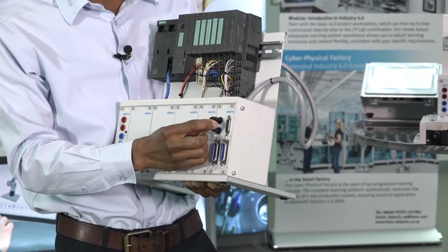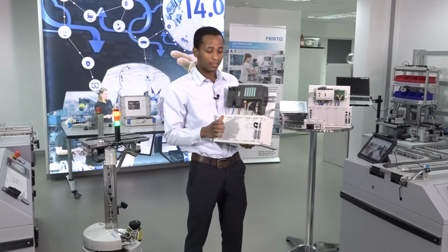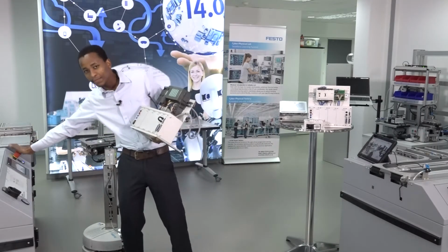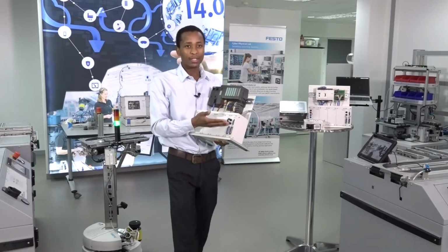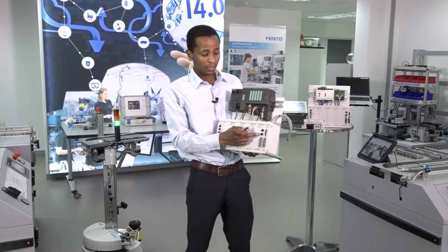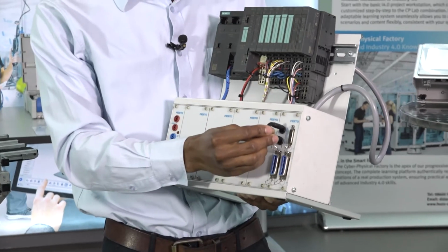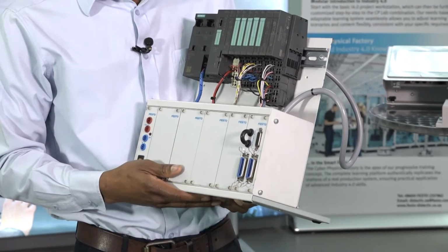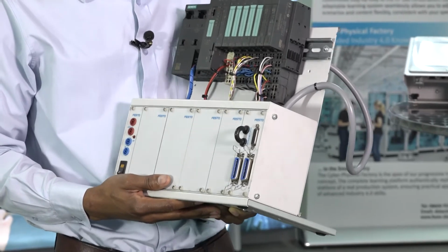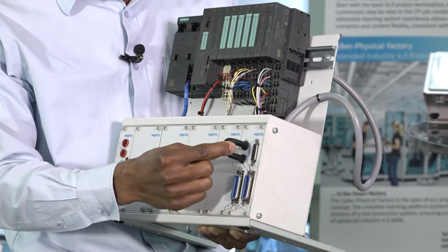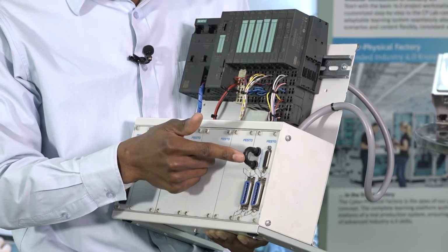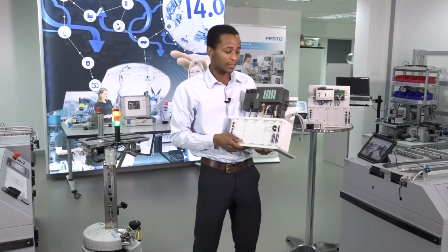Here, I can wire an emergency stop, so that if I press the stop, such as over here, this is an emergency here. Such an emergency will be wired to a connection here. If your system does not have an emergency stop, then you would use this bridge. This is just so that there can be connectivity between the 2 lines.